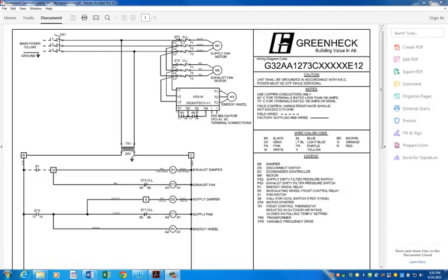Okay, so ST1, you can see that correlates to the line diagram down here. So anytime this ST1 is energized, these contacts up here close and tie our three-phase power to M1. So we look at that circuit, you can see that L1 is just jumpered over, L2 is jumpered over, L3, same goes for this VFDW.